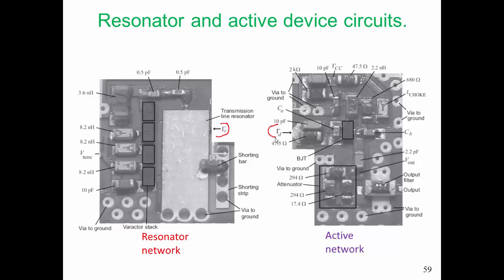Yes, we can use EM simulation as was done here with all the results that have been presented up to now. We use 2.5D simulation, but these components are not flat. They are little cubes and there's sidewall capacitance, and there are many things that we can't take into account. We also assume that our solder paste, for example, has 0 ohm resistance, and it won't exactly have 0 ohm resistance. So the art of microwave design is that we will use simulation, we will use intuition, and we will use measurements, and we'll use all of those to guide us towards a final product.